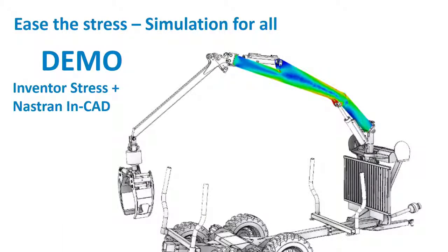So that was most of my PowerPoints, and my intention now is to swap to Inventor instead. Now I have some words to say first. And in this case, I'm going to check some typical examples of what you want to look into. Stresses at service load is a typical example. You might want to see stress at ultimate load as well. Buckling in this kind of problem to see that it will not collapse. It might happen way before you reach the yield limit.